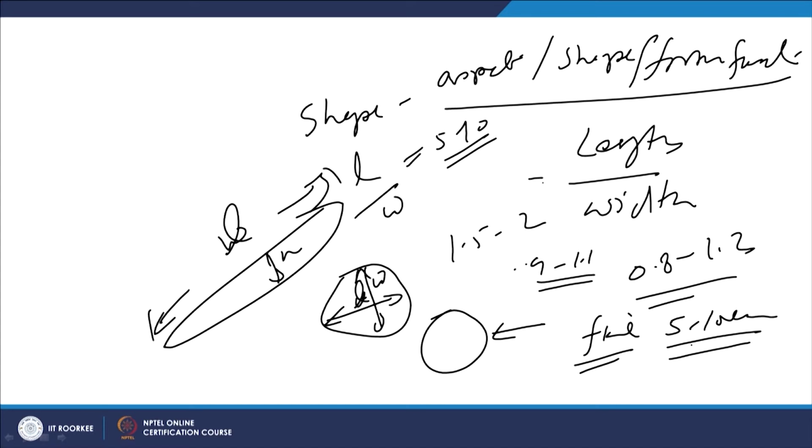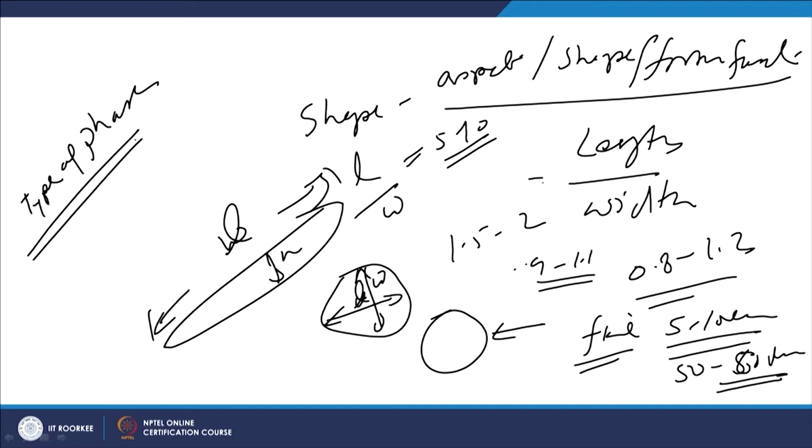Microconstituents will offer much better wear resistance as compared to the 50 to 60 micrometer grain size microconstituents. So the size and shape and the type of phases are the things that we try to quantify. For determining the type of phases, simple microscopy doesn't help, but we need to perform XRD analysis. So XRD analysis actually helps us to identify the various phases which are present.